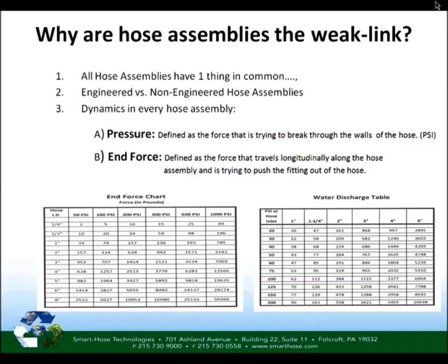A good example is a barge hose. If a barge hose is not properly supported with slings and the weight of the hose is hanging off the connection ports, this barge hose will fail quicker due to the weight of the hose pulling back on the fittings and causing premature failure. Another example is a hydraulic hose in a steel mill environment. Sparks are falling on it, molten splatters, there's no protection on it whatsoever, there's no cover. This hose will fail quicker than a hose concealed from such a harsh environment. Mean time to failure is directly related to the application.